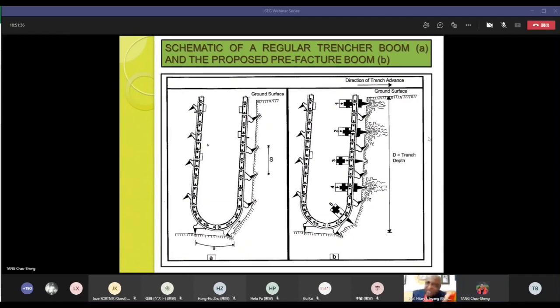Now, the hammer would hit at that point, and that point would deflect. The chain would deflect, and the impactor would then hit the rock and cause cracks, much like what you saw earlier with the experimental setup. Then it would be possible for the cutting bit next to that zone to remove large fragments. You see, the cutting bits are the ones in between the hammers. They would come in to excavate material that is already fractured, and the required cutting forces would be low.